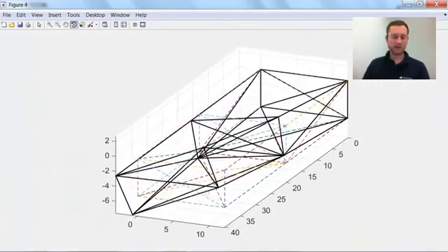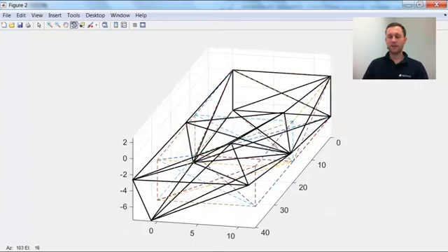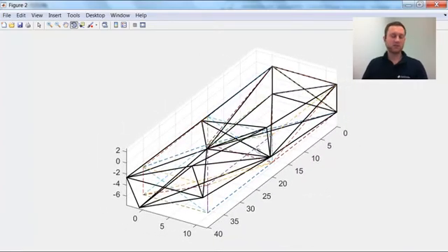And what you could do is calculate the angle between these two nodes, compare it to that one, and see how much your chassis deformed. So the main message that I want to bring you today is, it's quite easy to set up a truss framework. Just start from scratch, design the number of beams, take the coordinates from your CAD system, set up an easy model, and then you can already try to optimize a bit where trusses are really helpful, where they bring stiffness, or where they are just a waste of weight. This is very easy using that method.